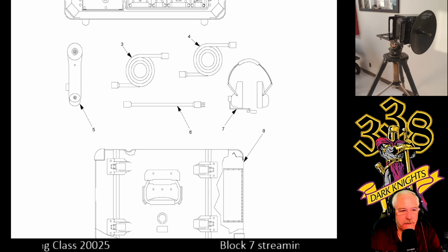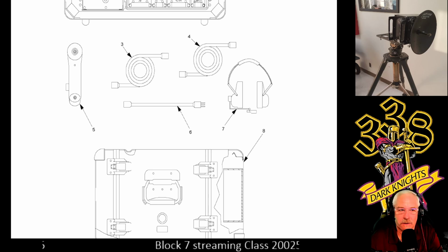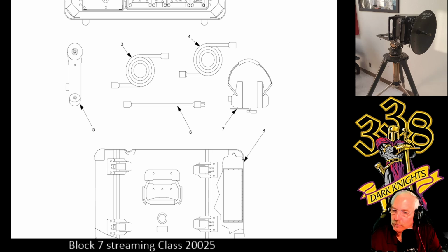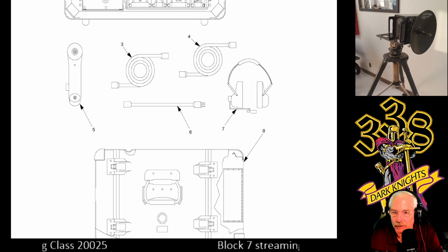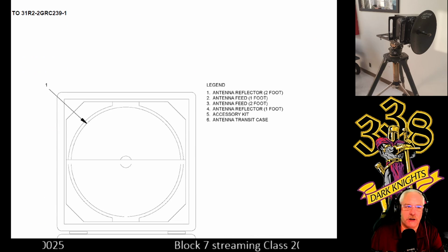Let me caution you about the headset. When you plug it into the RF assembly, sometimes if you don't plug it in the correct way, it will squeal on you. I suggest very highly that you do not have those on when you're doing that. And also do not have them on when you're doing the test tone checks. There is no volume on that headset, only the speaker. Same with the handset. Don't put it up to your ear when you're trying to do test tone. Safety precaution. Protect your ears.